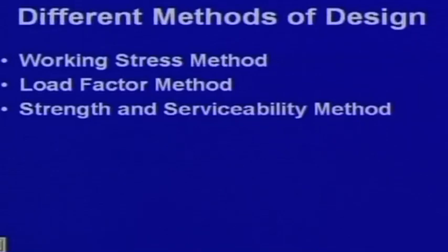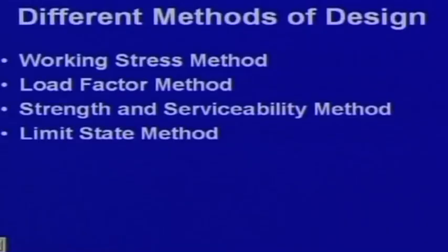The third one is the strength and serviceability method. We shall consider strength as well as serviceability. In the first two we are considering only strength, but for the third one we shall consider strength and serviceability both. And finally, we have the limit state method, which is the present day practice. We use the limit state method extensively for our reinforced concrete design, and that we shall study in this particular course.